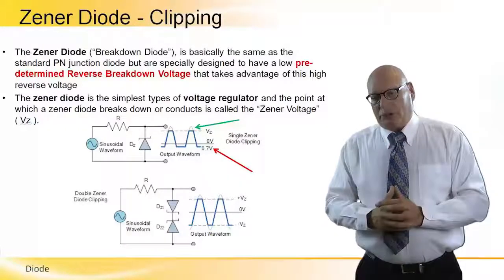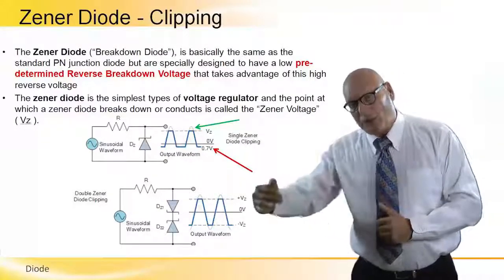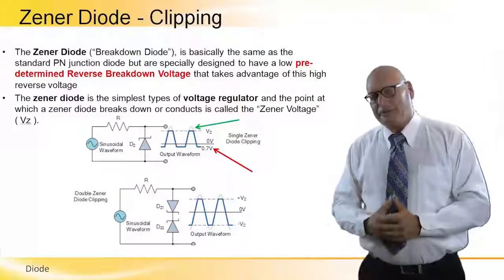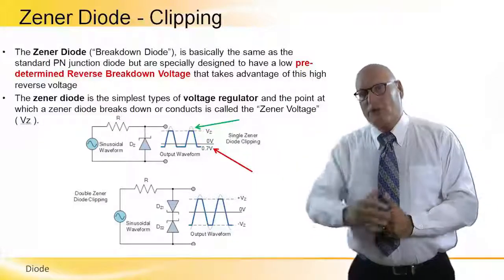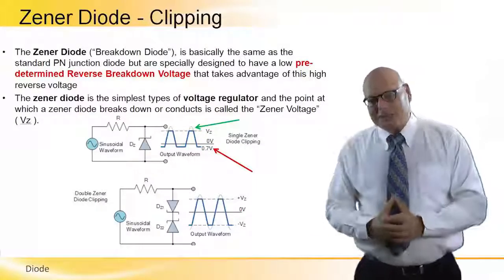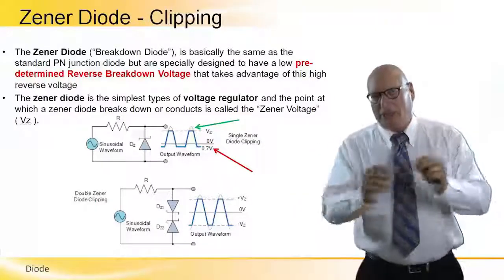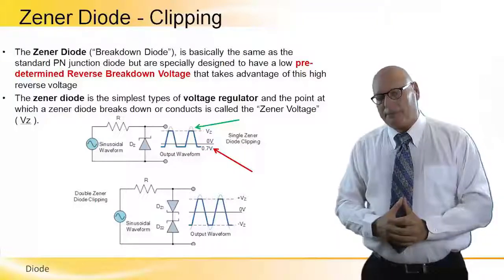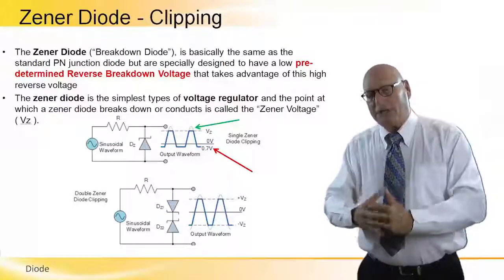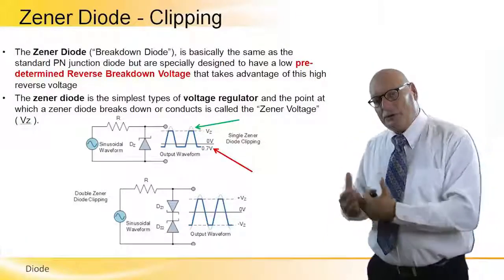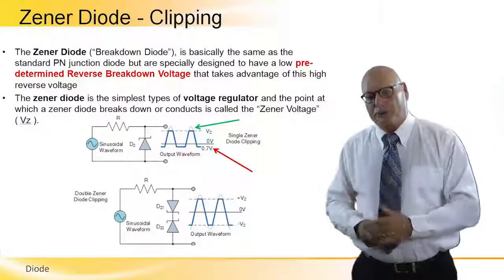In the other direction, when the sine wave goes negative, crossing the zero axis, then the bottom diode conducts and drops 0.7 across it, and the top diode basically does not conduct up to the point of that rated voltage, again specified in the technical specification. And the same explanation as I described before holds in this case also. So this is the reason we get a symmetrical waveform at the output, as opposed to the top one.